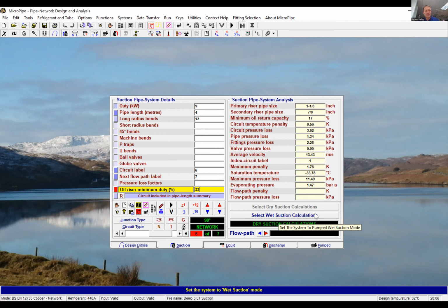That's the argument they would give, but we're going to increase the system penalty. So I love to design. I like to see that penalty there, 1.78. There's only so far you can push with a low temperature system, but medium temperature, I like it as low as possible, because that's going to benefit everybody in the long run.